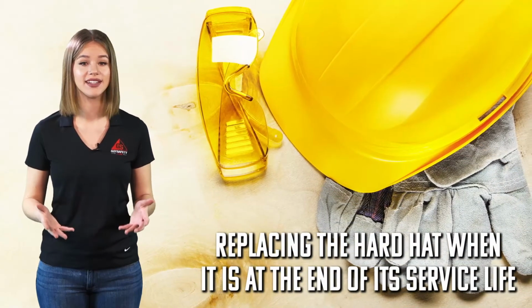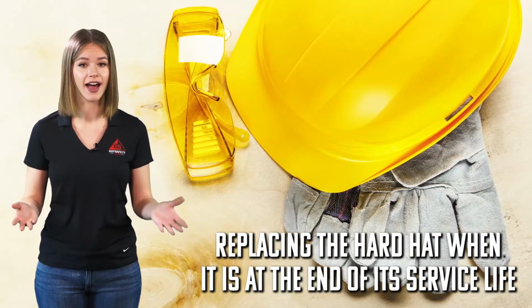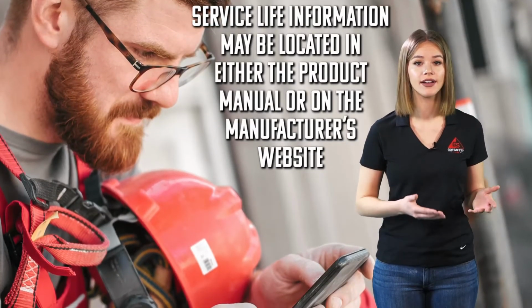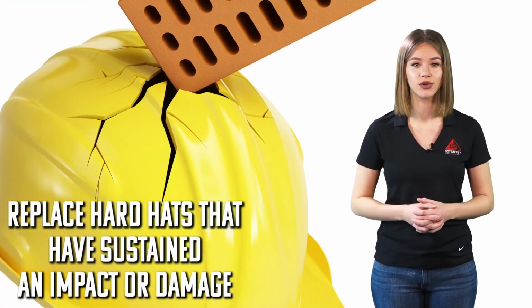Replacing the hard hat when it is at the end of its service life. This will be dependent on the manufacturer, but typically ranges between 2 to 5 years. Service life information may be located in either the product manual or on the manufacturer's website. And replacing hard hats that have sustained an impact or damage.